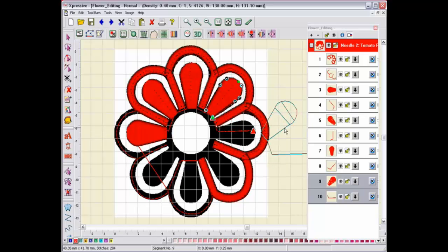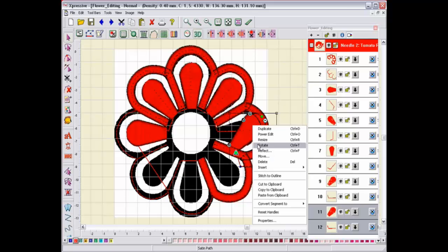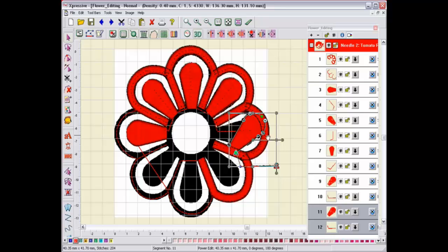To place these duplicated items into the design, left-click. After you left-click, you'll see the wireframe is still attached to the mouse. Press the Enter key to end duplication of the selected segments. Duplicated items behave the same as copy and pasted items.